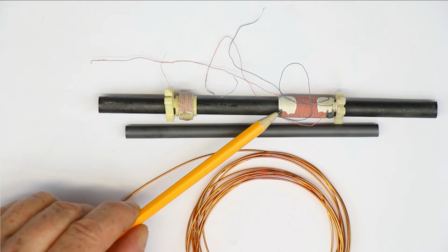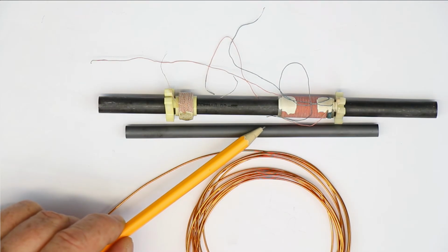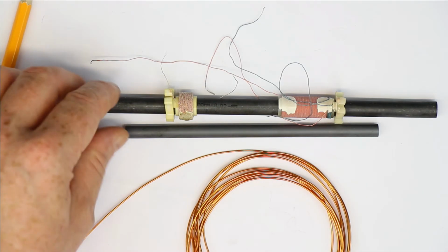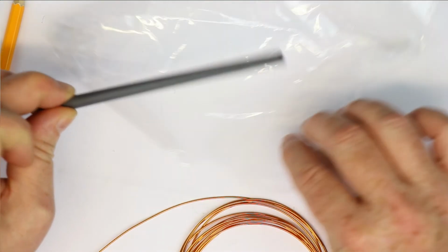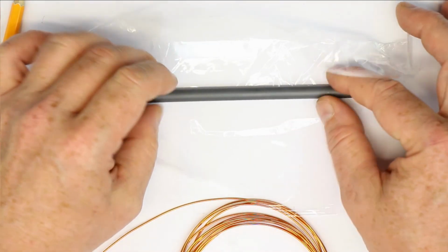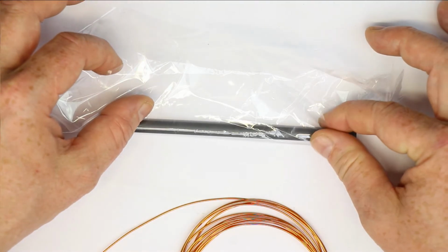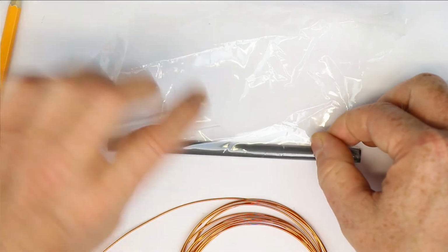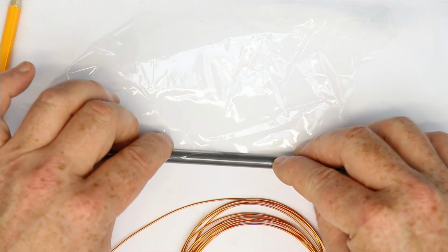We should not choose any plastic. If we get some Teflon or polypropylene foil, that would be good, but it's not easily available. But the next best thing is simply cellophane, which is still used for packing food. You should be sure that it's really cellophane foil or film, and this is a relatively good dielectric material.